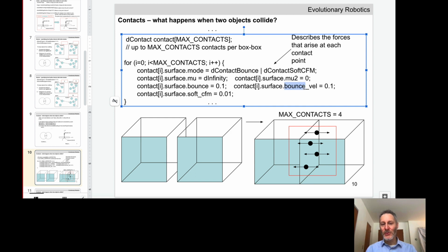You'll notice the mention of bounce here. We can imagine two objects coming into contact with one another, and those objects may be bouncy or not bouncy. Imagine two rubber balls coming into contact with one another. Two rubber balls are going to be pushed apart with large force. They're going to suddenly have velocities. They're going to start moving in the opposite direction. Imagine instead we have two steel ball bearings that come into contact with one another. They are very not bouncy. They will hit one another and decelerate, but not necessarily accelerate in the other direction.